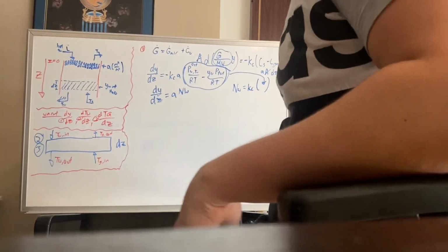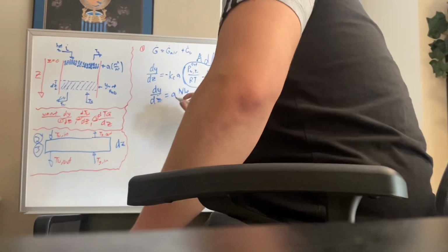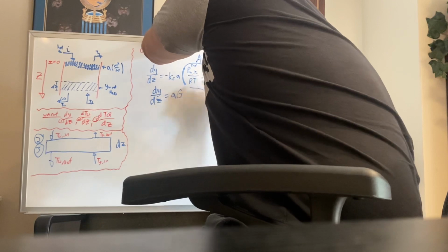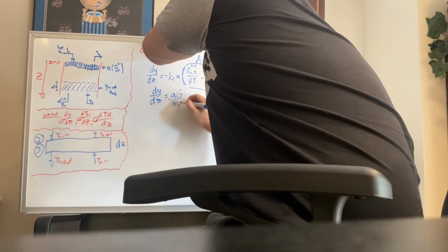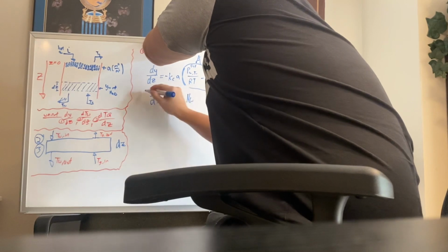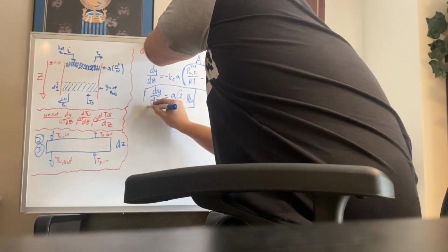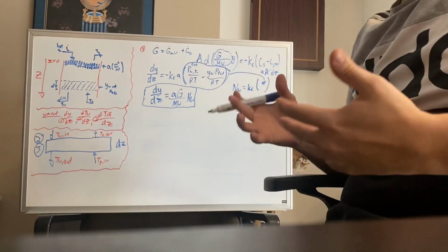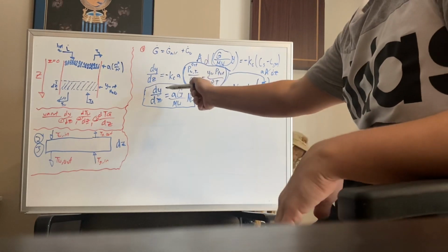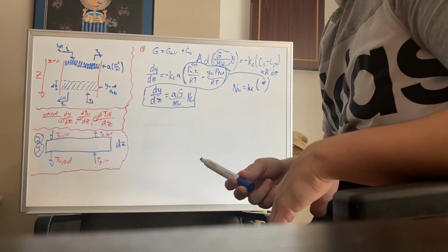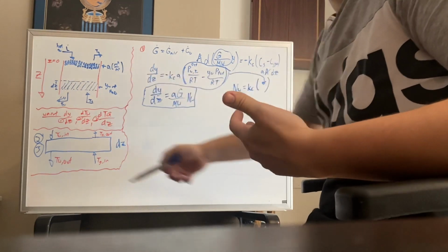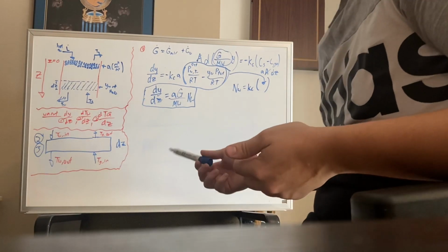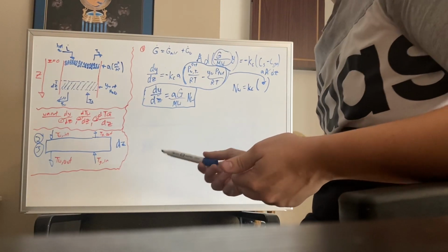So this is actually going to be this molecular weight times the gas flow rate that we had up here, all over the molecular weight of water, multiplied by the flow of water. And so that's going to be our first equation that we have for differentials that we're going to be solving for. And this represents the rate of change of the mole fraction of water with respect to the rate of change of the area of this going down the cooling tower. And we will end up using this later when we solve for our second and third differential equations as well.